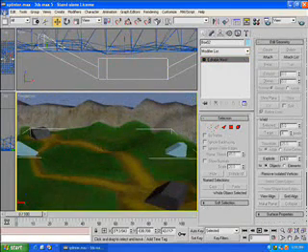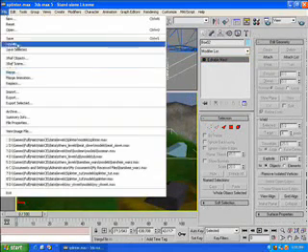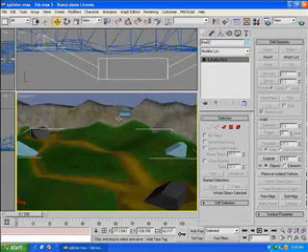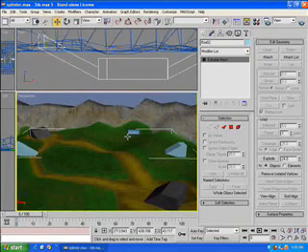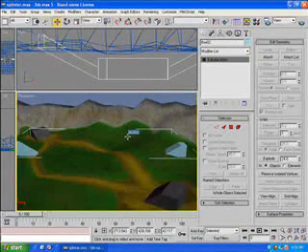At this point we're going to save, and in the next step we're actually going to be doing the same thing that we did with the bases, where we attach the tunnel system to the level itself, delete the faces around the entrances to the tunnel, create new faces, and then we'll be exporting it and testing it out in our level.